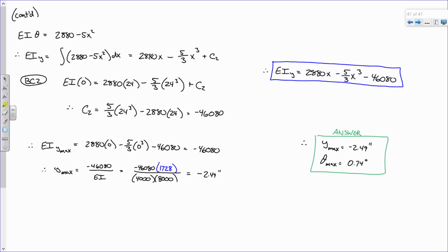It's the same thing if you're designing an airplane wing. We've had problems like this before, for instance, for you mechanical engineers, when we looked at torsion. There were instances where we had a torsional shaft where we had to limit the shear stress to 10 KSI, but we also had to limit the angle of twist to 2 degrees. So based on those two limits, which controls? And from there, it wasn't the same story, right?